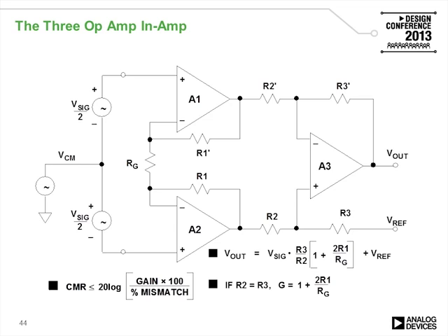The subtractor stage only removes the common mode voltage without adding any amplification. The resistor RG sets the gain, and in the most common instrumentation amplifiers, this resistor is external. Precision instrumentation amplifiers have this resistor internal for excellent gain drift.